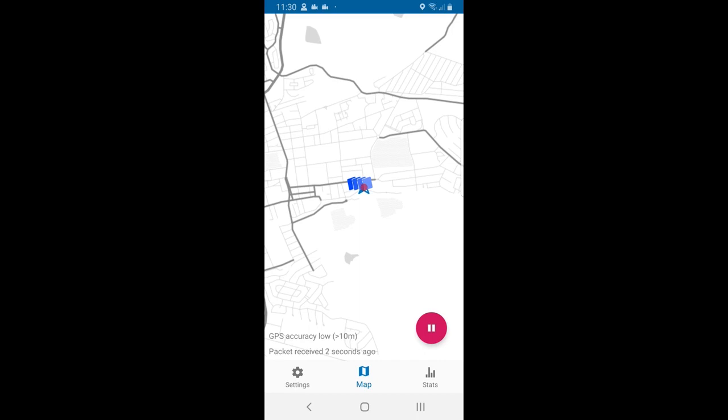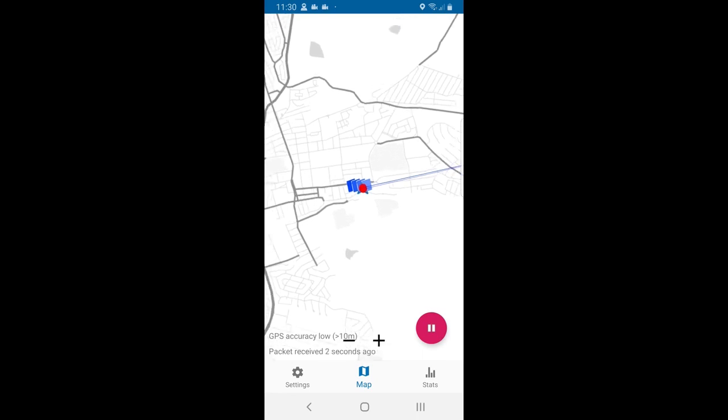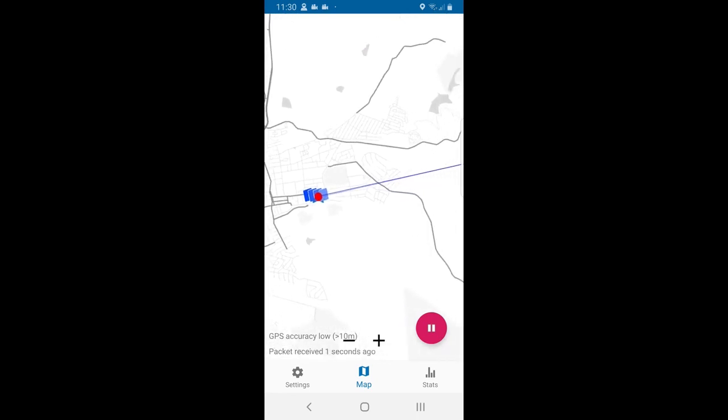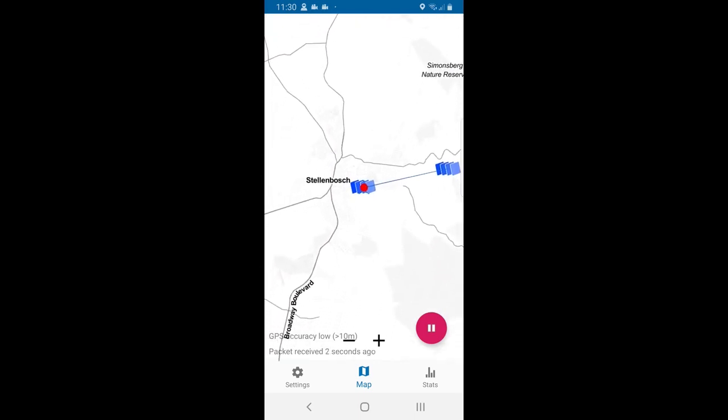On the map, we can then draw a marker for every message and color them according to the signal strength. A warm color like red is a strong signal. A cold color like blue is a weak signal. This will create the heat map of our coverage. Because the metadata contains all the gateways that received our end device, and sometimes the location for these gateways, we can draw markers for these gateways and lines for the path that the radio signal followed.